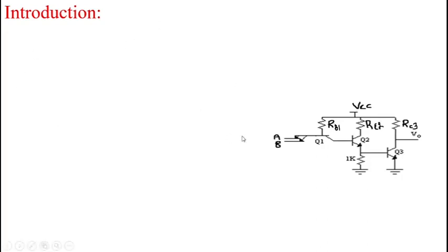This is the circuit diagram of the passive pull-up network. In this circuit we are giving both the inputs as 0 0. At that time the emitter-base junctions of the diodes are forward biased and the collector-base junction diode is reverse biased. Therefore, the Q1 transistor operates in the active region. Clear? And the output of this Q1 transistor is logic 0.